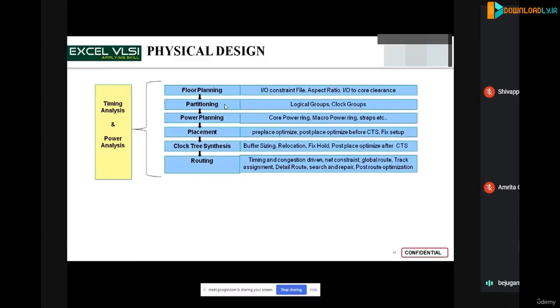So with the placement stage, a parallel operation of optimization also happens. That is again like you are reducing the timing, power and area. So basically if you are considering an integrated circuit, you need to bother only about 3 parameters, that is the timing, power and area.